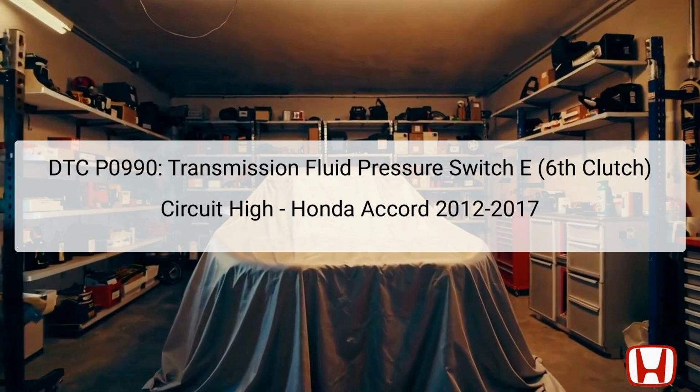The Diagnostic Trouble Code, DTC P0990, indicates an issue with the transmission fluid pressure switch E related to the 6th clutch in the Honda Accord models from 2012 to 2017. This error occurs when the circuit experiences a high signal, affecting the proper shifting of gears within the transmission system.